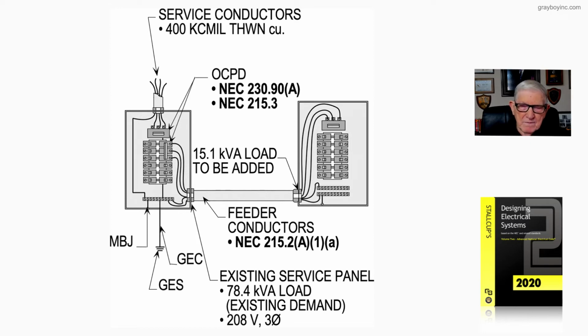And 3, the feeder has overcurrent protection in accordance with 240.4, and the service has overload protection in accordance with 230.90.